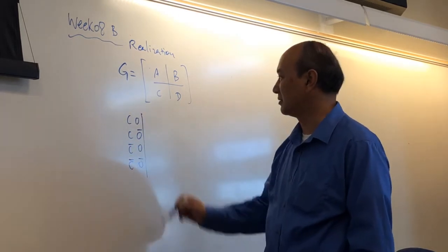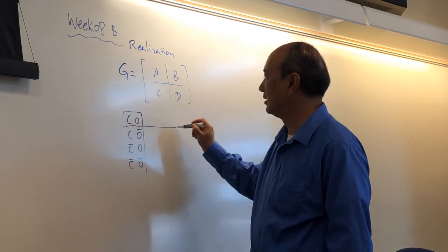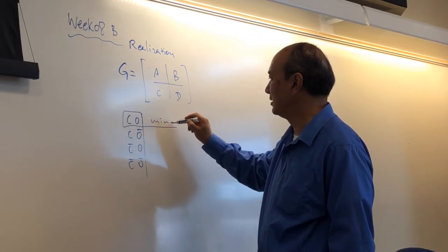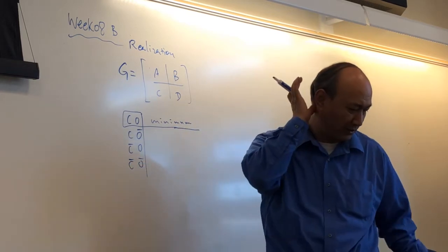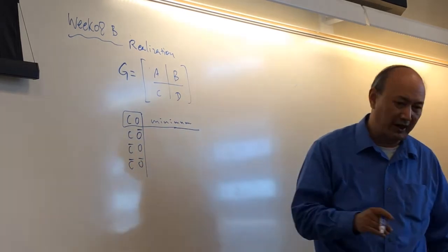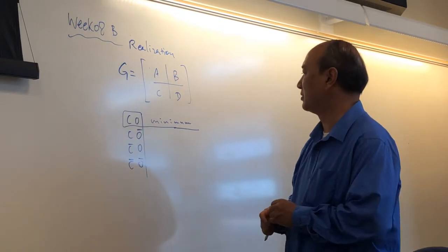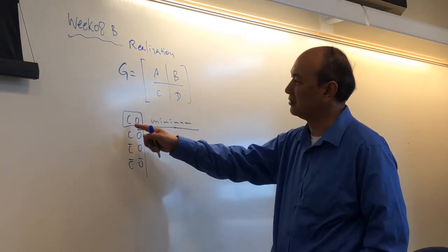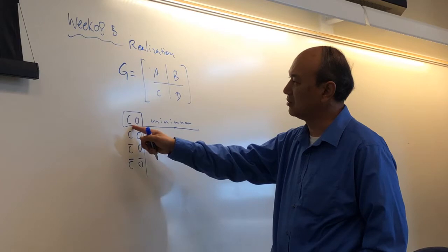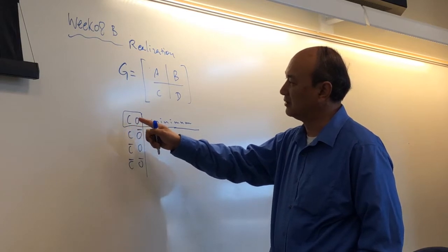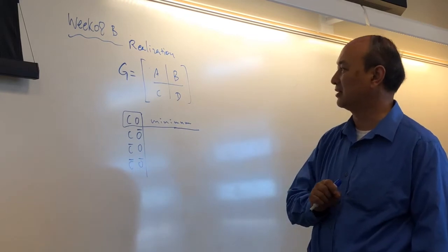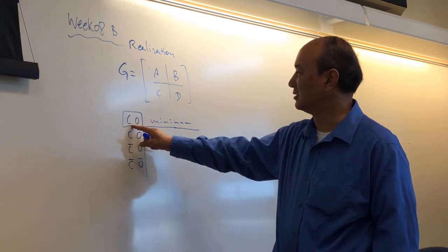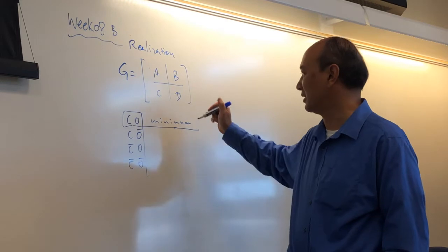Subspaces. Only this is called minimum, okay? This is called minimum. So for this minimum, we had a principle about how to do this minimum realization. Basically, you need to get the controllable and observable both fully ranked, and then you will be able to get the minimum.